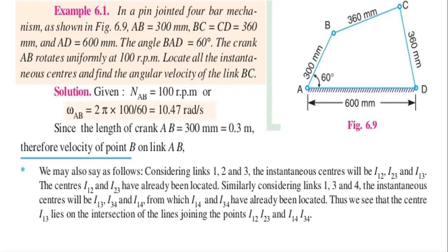Similarly, considering these three links, that is 1, 3, and 4, the instantaneous centers will be I13, I34, and I14. I14 and I34 have already been located.